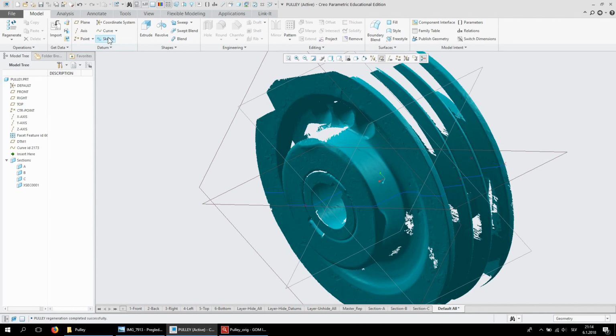I recommend that you use this, not that you go directly to revolve or extrude, but that you first create a sketch and then do that, because it sometimes happens that you might have some problems. You have to maybe create something new outside of the sketch, and if you are using this, you will have to just delete that sketch and start over. But if you are using just sketch like this, you can leave that sketch half finished and then restart again.